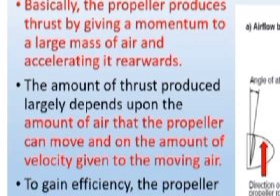If you want force, which is thrust here when it comes to the propeller, then you need mass, that is the mass of air, that must be accelerated rearwards at higher velocity, such that when you multiply the huge amount of mass by the velocity, you get enough force, a thrust, to accelerate the aircraft forward.